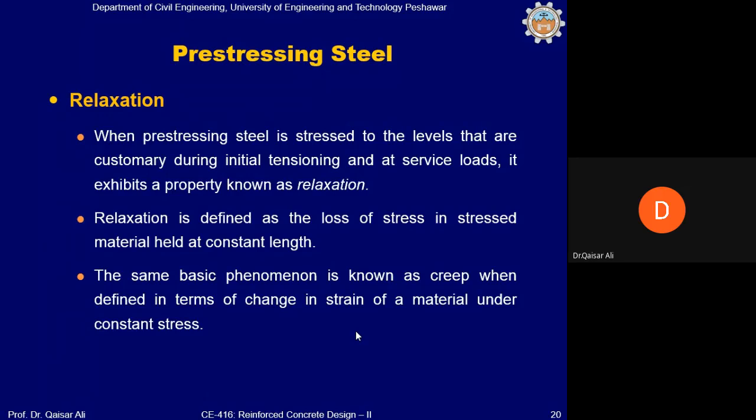However, if steel wire or cable succeeds in regaining its original length partially or fully, there will be a loss in precompression stress, and this loss in precompression will reduce or eliminate the beneficial effects of precompression.